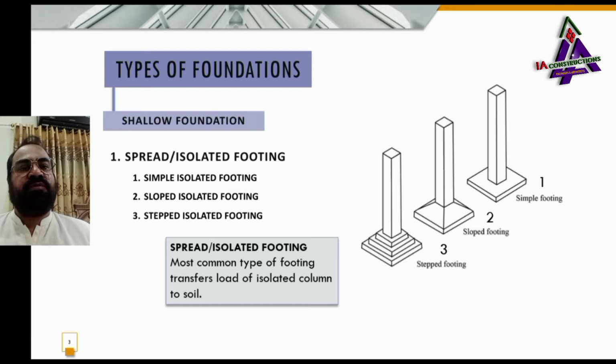Number 1, simple footing. It is also called pad footing. Number 2, sloped footing. A slope is provided on the top of base. Number 3, stepped footing. 2 more steps are provided on the top of base.